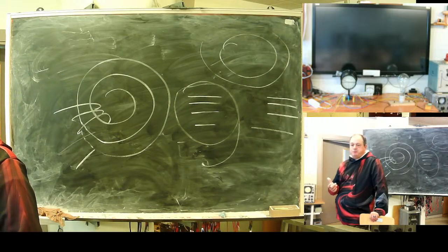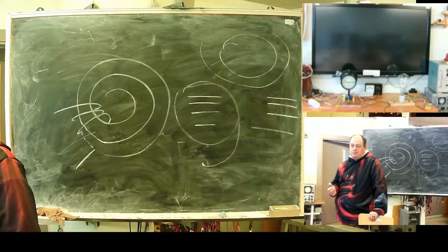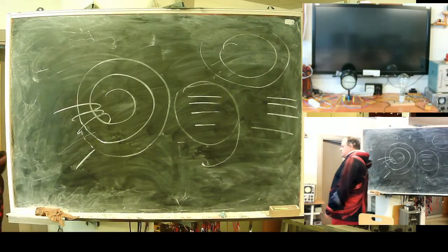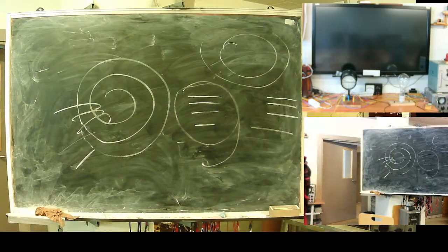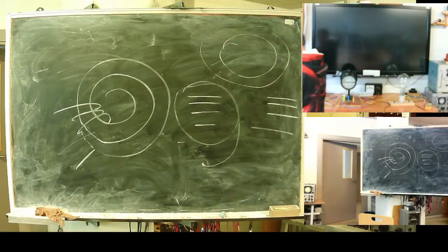And a pure disaster is an attempt to use ferrite. Magnetic material designed for pulse transformers. This will be a disaster because they have kind of rectangular magnetic loop. Not good.